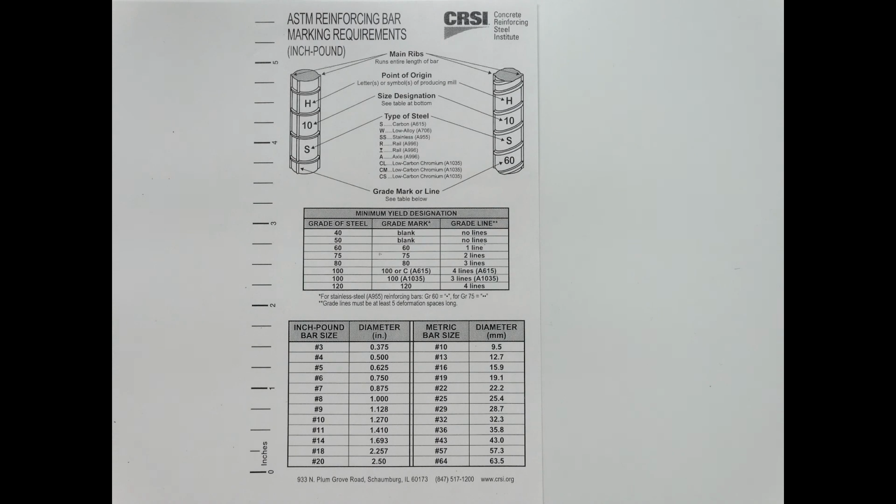So if you calculate out here at D, D from the face of the support, that you need a stirrup every 6 inches, just run that out until V is equal to V sub C. Then you pick up the minimum spacing till it's equal to V sub C over 2, then you don't need anything. The calculations are done just like this.